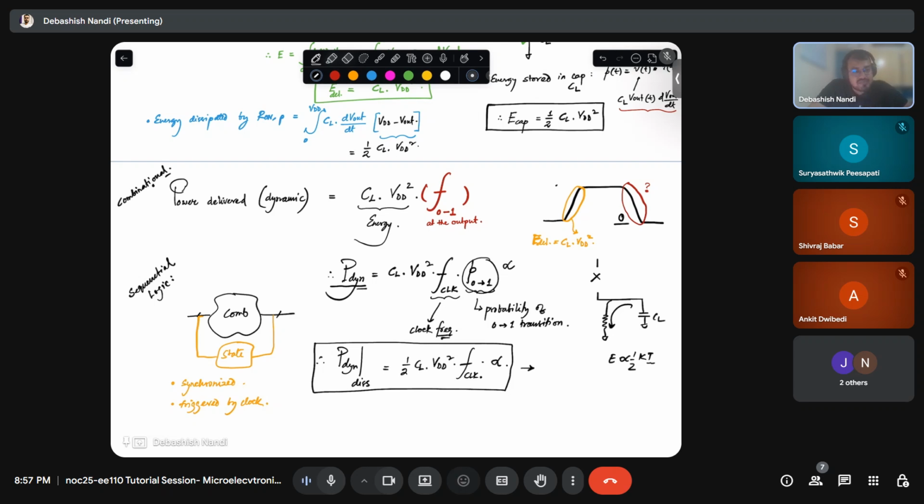Now, if you increase your temperature, the Ni, or the intrinsic carrier concentration, increases so rapidly, almost exponentially, that your semiconductor is no longer a semiconductor. You cannot use it to turn on and off. It will just be a piece of metal wire, right? So you lose all of the good things of the semiconductors.